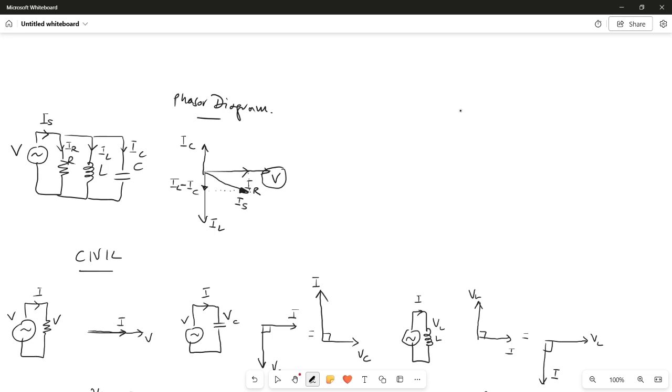Okay, to calculate or to draw my admittance diagram. So it's the admittance diagram for a parallel circuit. So remember my conductance is 1 over R. Okay, and then I've got my susceptance. So my BC is 2 pi FC. Oops, pi's got only 2 legs, not 3. And my inductive susceptance is 1 over 2 pi FL, right? And again, in this case, my inductive value has more significance, is larger.